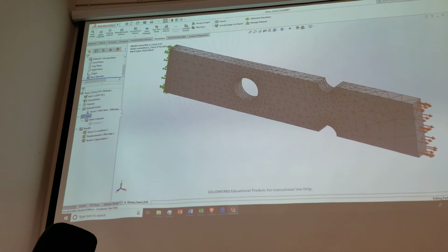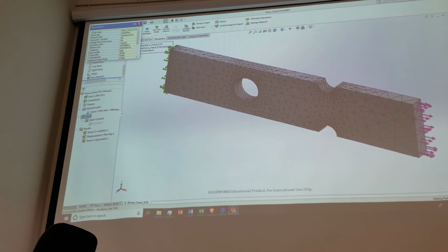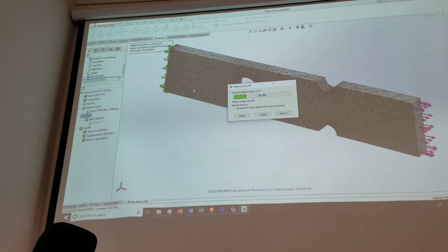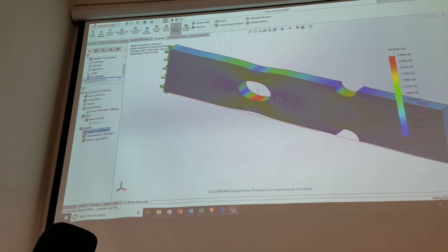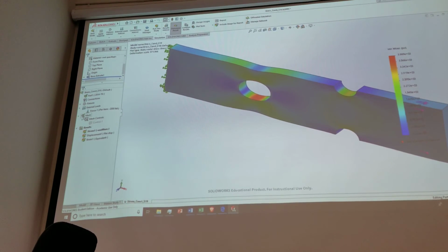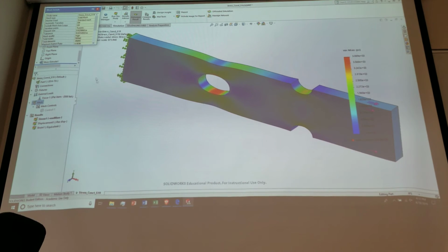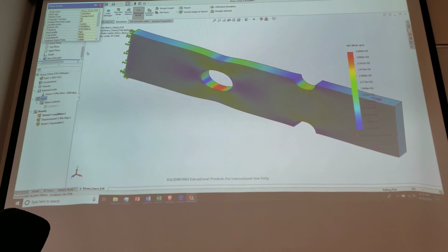Okay. So I can look at this current mesh here, for example, if I want to look at some details on the mesh. It looks like I have 26,000 nodes here. If I just run this again, hold on. It gave up on me, didn't run another time because it was happy with its convergence. So it's not going to be different, darn it. Actually, it did, it increased the density of the nodes by a factor of 2. So it must have run twice.